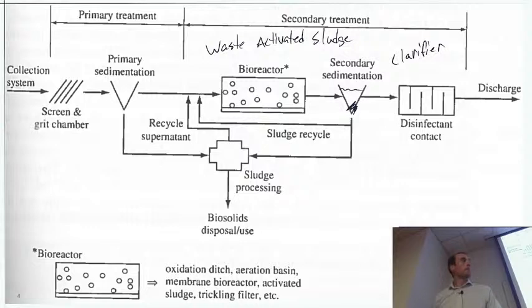We could use UV. An example here would be our South Baton Rouge wastewater treatment plant discharges chlorinated wastewater, but it's heading straight into the Mississippi River, and the flow differential there is such that it's getting so diluted that we couldn't harm a fish if we tried with the chlorine adding to it. And so we don't actually have a chlorine discharge limit in that scenario.